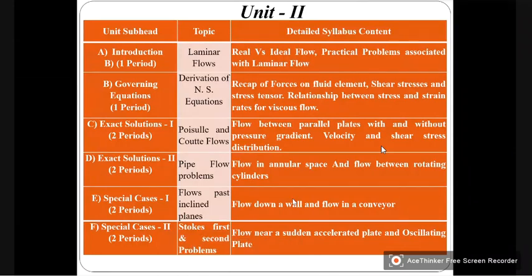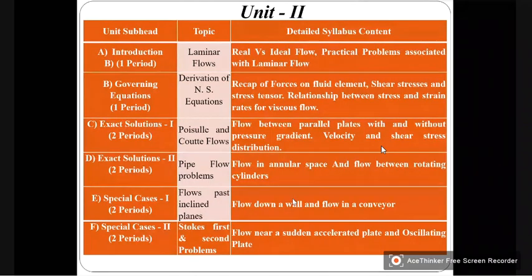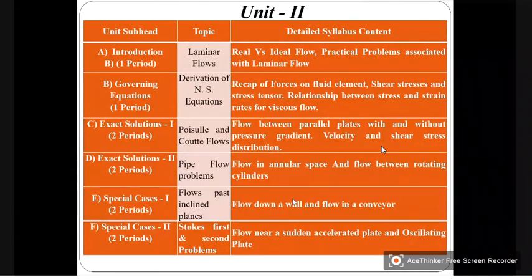while we have neglected the shear stresses in the case of ideal fluid flows because of the absence of viscosity, the same cannot be considered here because it is a real fluid, so it has certain viscosity, and due to that viscosity, the shear stresses will also be present. So therefore, while developing the equations for real fluids, we have to take into consideration the forces due to shear stresses. So that is the basic difference. But for that, the same procedure, everything will be same.